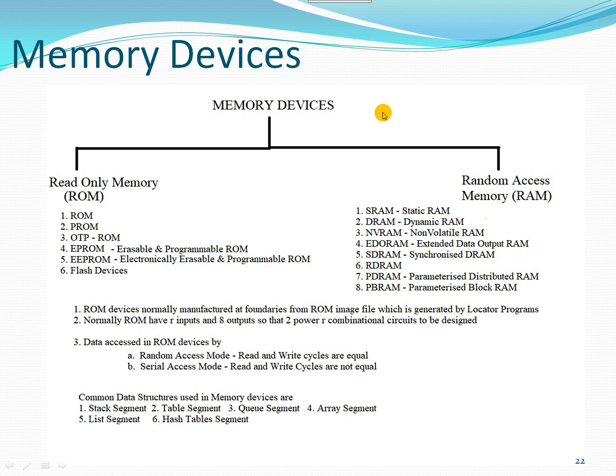For the ROM we will be having PROM and OTP ROM, EEPROM, E2PROM and flash devices. PROM means programmable ROM. Once the ROM devices are manufactured and programmed, we cannot change them afterwards. So whatever programs we want to use in an embedded system as non-changeable can be used with the help of PROMs.